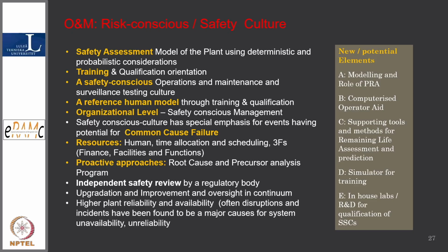Support tools and methods for remaining life assessment are required, because we should have clarity, especially on certain selected components, about what their life is. Suppose some component fails and it takes away 7 to 8 days of availability, then from a reliability point of view also, remaining useful life is important. But suppose some component fails and safety is compromised, then in that case we must have the remaining useful life.